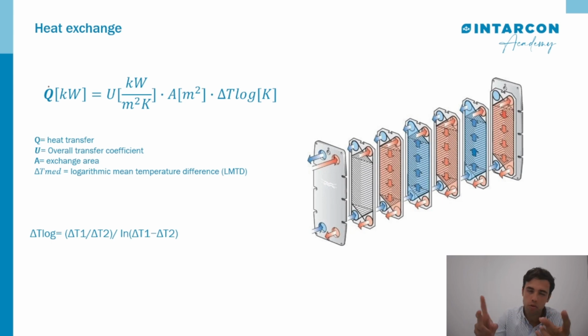We also have two main types of plate heat exchanger, those with co-current and counter-current flow, where the entry is totally different, and the transmission in the second one will be higher because the flow is counter, so the overall transfer coefficient is bigger.